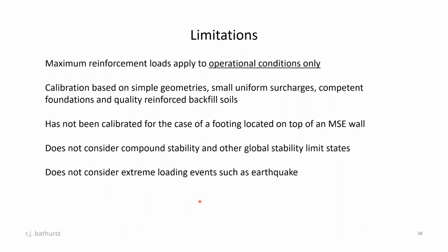You only use it to calculate maximum reinforcement loads under operational conditions. You don't use it for limit states that are at incipient collapse or black swan events like earthquakes or tsunamis. It's limited to simple geometries, relatively small uniform surcharges, competent foundations, and soils that conform or meet the specifications for quality granular soils that you find in AASHTO and the Canadian codes.